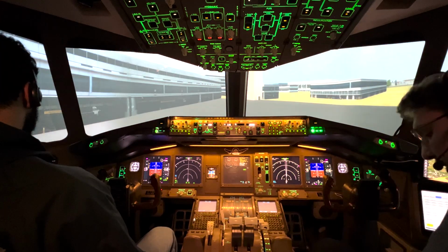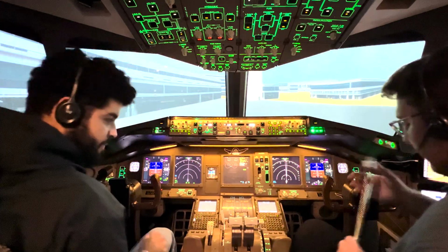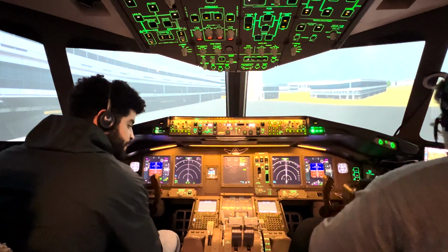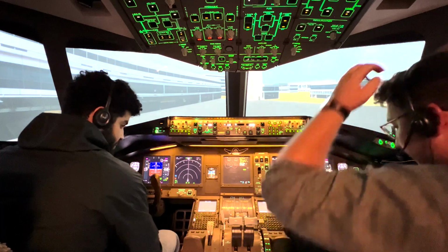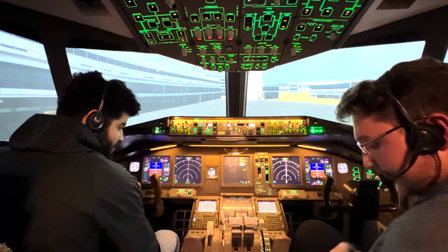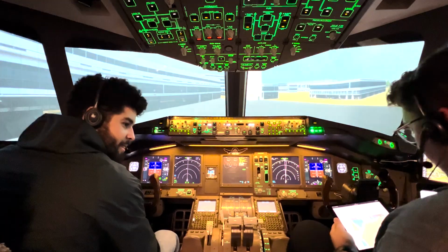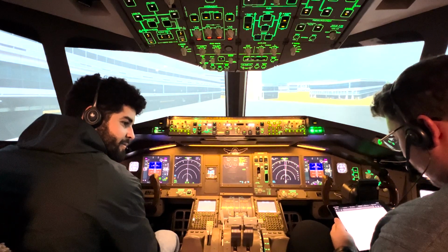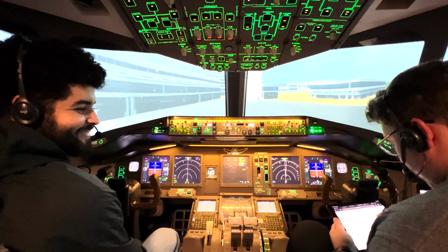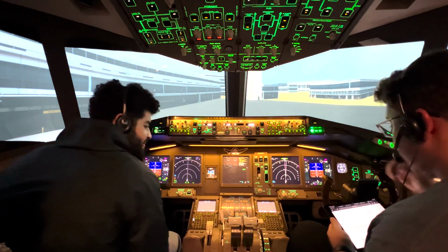First things first, I'm going to get you familiarized with the flight management computer. This is our flight management computer, also known as the FMC. What the FMC does is it allows us to program a flight plan into the computer and allows the plane to follow that flight plan. So we're going to start off by programming our departure, which is the LANU 6D departure with the LANX transition. And we're departing on runway 34. So we'll go ahead and start that.